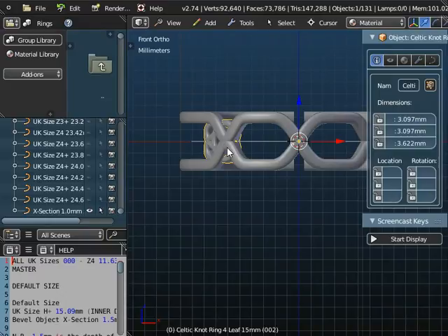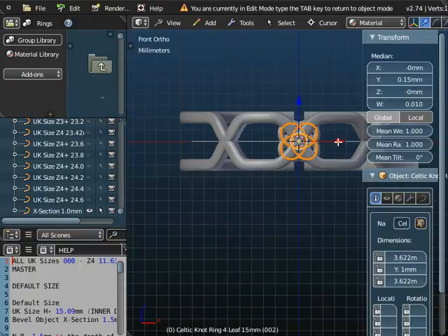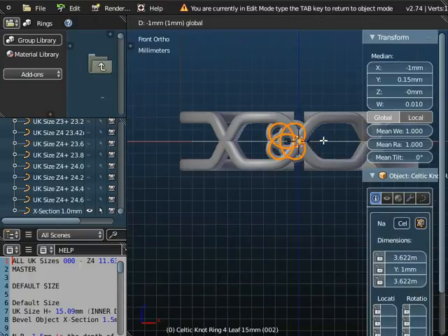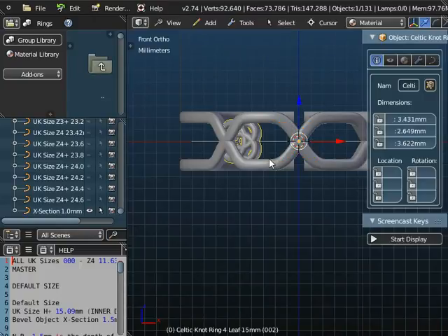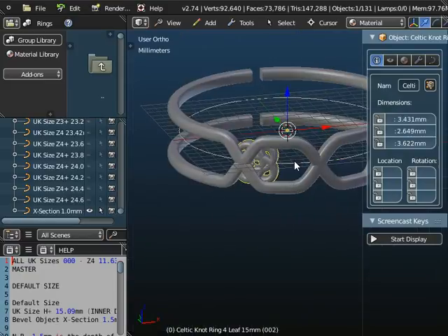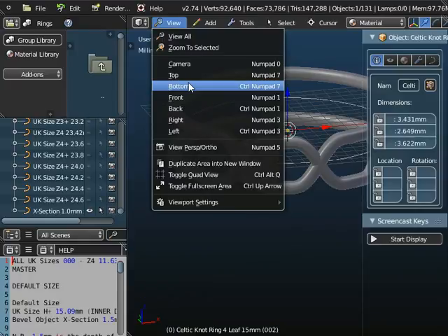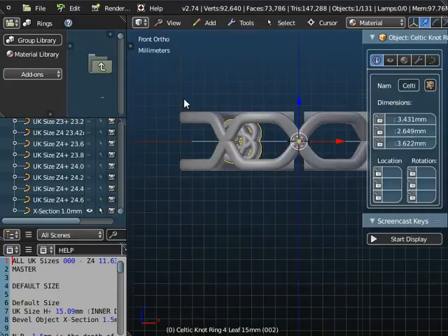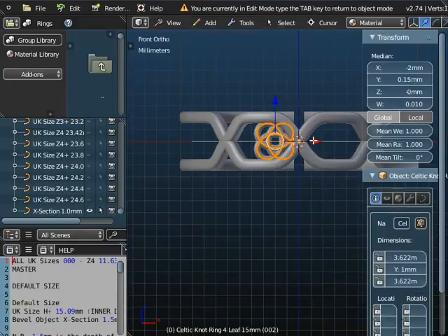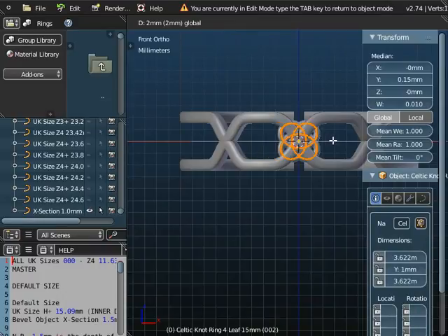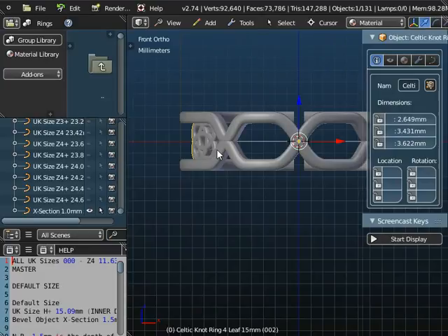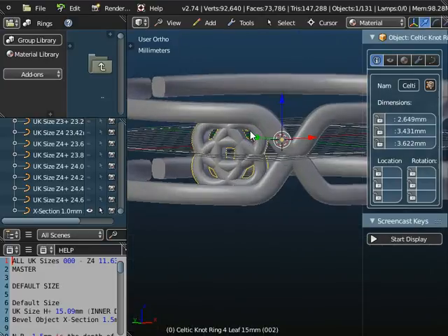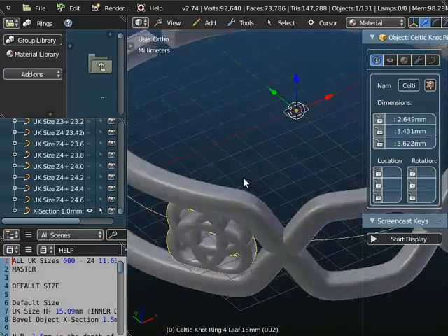If I press the Tab key to go into edit mode and try moving this object a couple of times to the left and press the Tab key, okay, it's moving it in the opposite direction, as you can see there. Sometimes things work back to front when you're working with this. So if I go to front again and move it back, I moved it 2 places before. If I move it another couple of places to the right this time, you can see that's now positioned it at the start of my ring